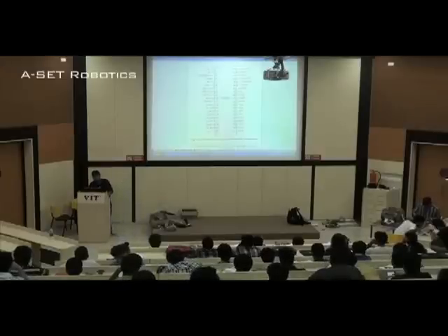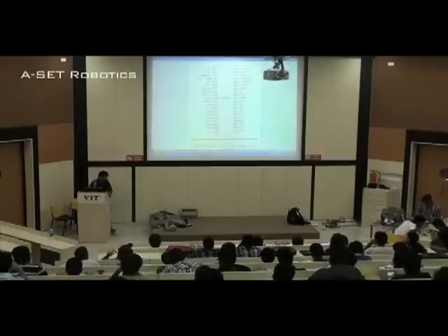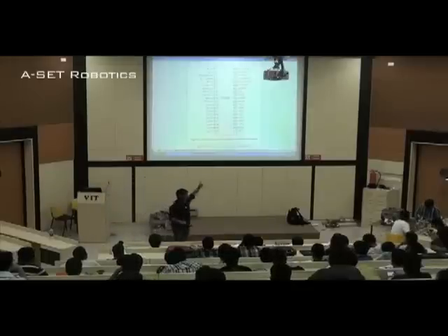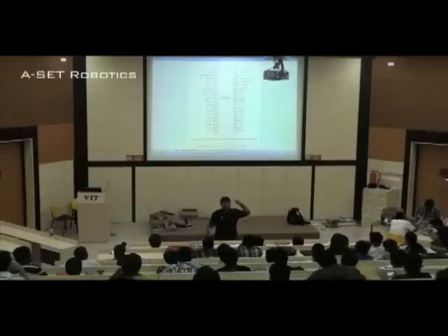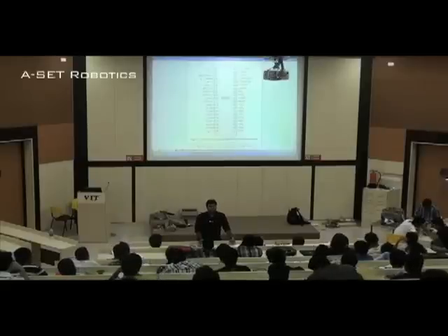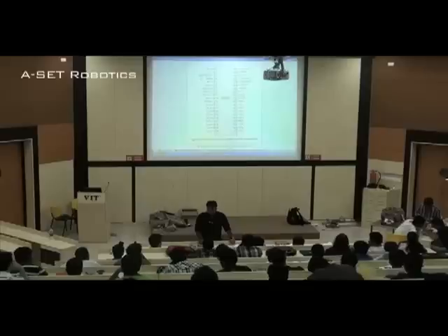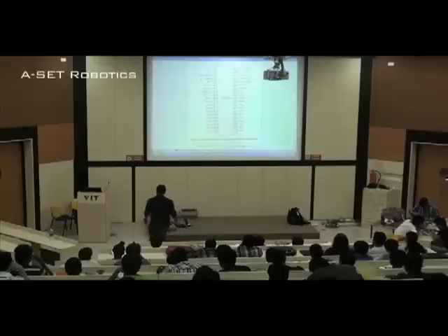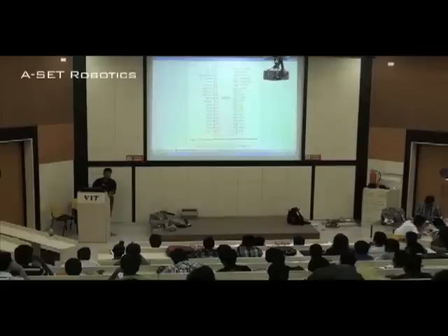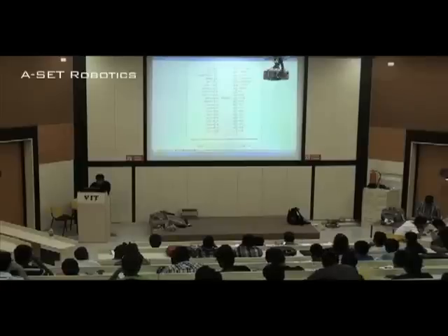All the pulses would be coming into this X1 and X2. And if your microprocessor is of 3 megahertz, the pulse that will come to X1 and X2 would be of 6 megahertz, double what the microprocessor is working at. Correct? It is for accuracy, so that the microprocessor gets the clock pulse and works perfectly fine. You know the working of SOD, SID, TRAP, INTR, INTA. So we are done with this side except for RESET OUT.